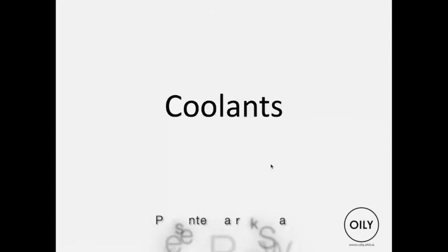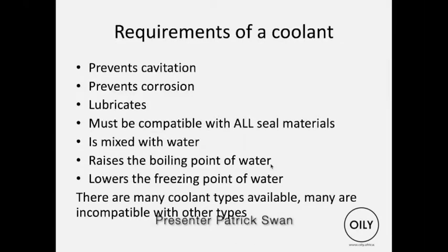We can do coolants. Requirements of a coolant: it must prevent cavitation and corrosion. It must lubricate moving parts in the system. It must be compatible with all seal materials, polymers, pipes, hoses, everything.